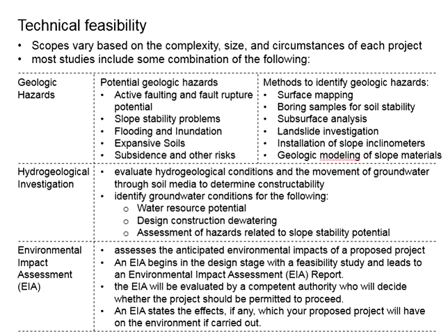Sometimes the technical feasibility investigations not only cover the proposed development regions. You may need to evaluate the implications of certain construction methods towards the nearby structures. For example, you are doing the development at the deep peat areas. That means the soil is mainly constituted of peat, which is a type of organic soil containing high amount of humus and also water. In order to minimize the settlements, normally soil consolidation is carried out, but this requires time.